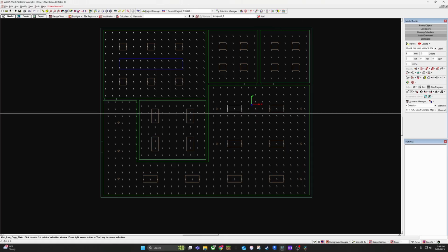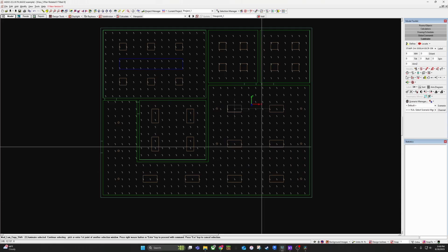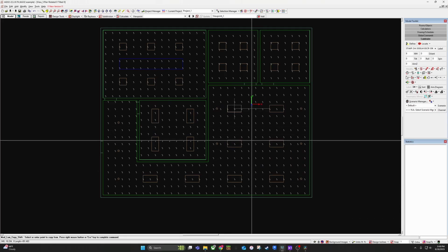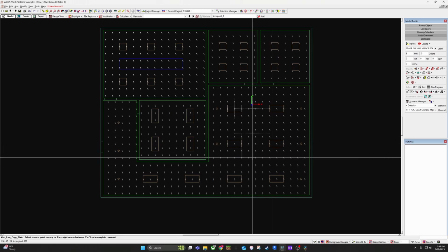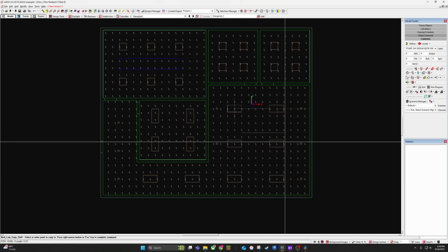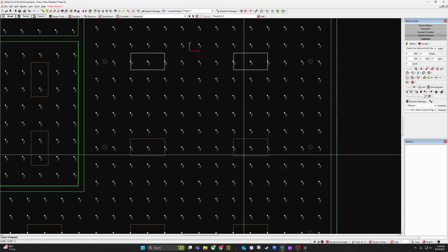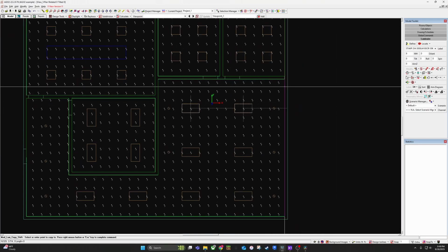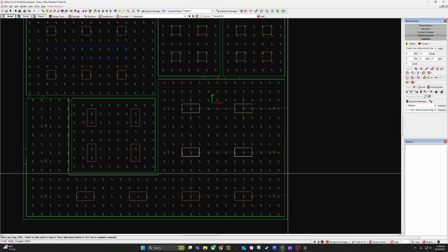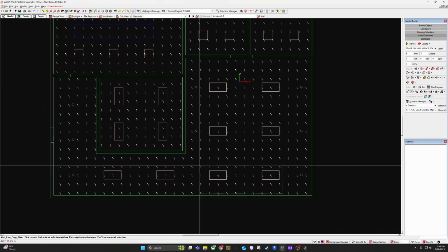If you want to copy that light, copy Luminaire. I usually choose window. Status bar says right mouse button to proceed. Left mouse click. Right now we're in ortho mode, so we can go in a straight line. Put it right here in the middle. And I'll just copy it all the way down. Do the same across.